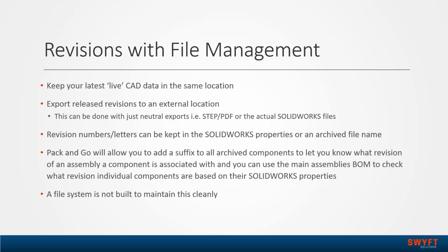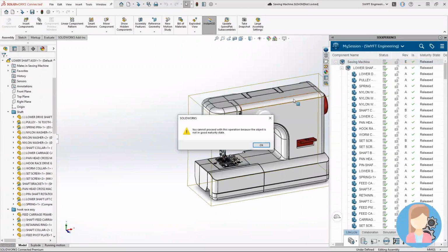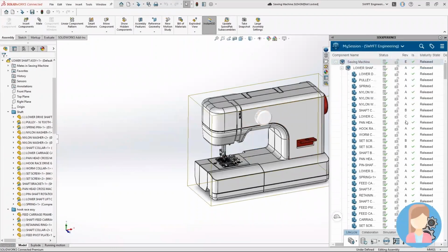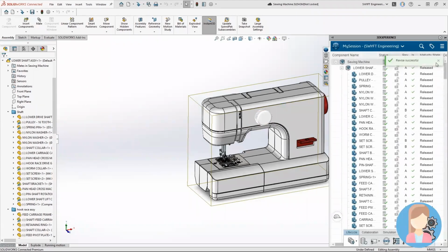So in terms of data management, this is another one that I was demonstrating in the video. You can see that it has Rev E there. As we go in and try to edit it, we see that it's released now, so we get confirmation of that engineering release. We can just click new revision. That'll bring up a preview of what revision is going to be next. And then I'm able to go in and create that new revision and pull it into my system. All past revisions are stored, so you can always go back in history and see what revision is, what state of the design.